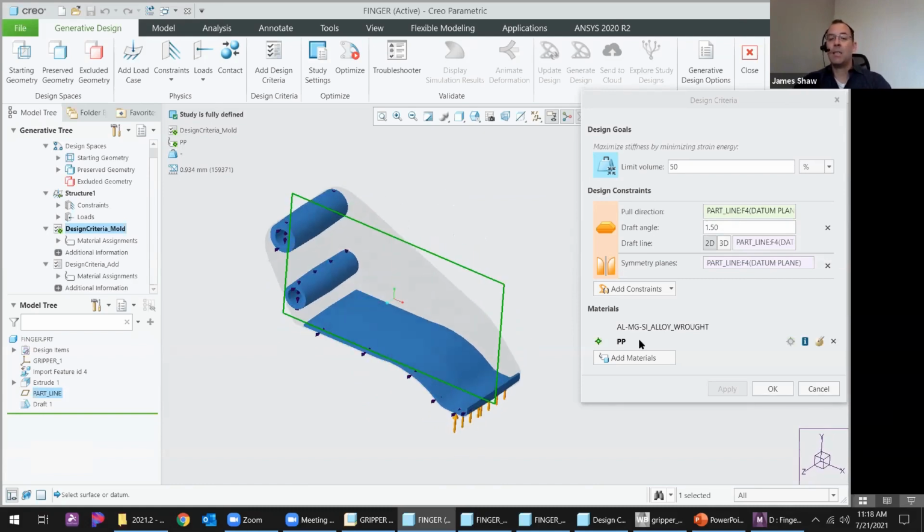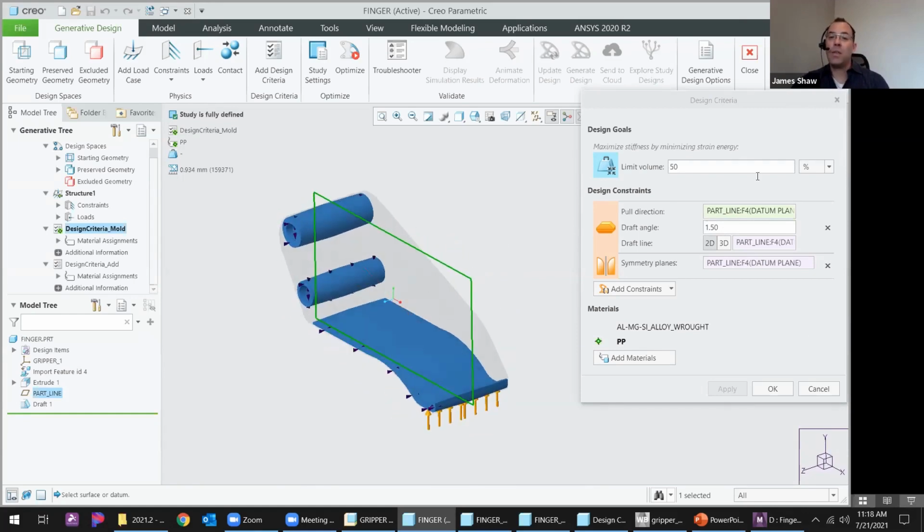In this case, I'm going to target a very economical polymer. So I'm going to go after polypropylene, PP. I'm going to hopefully reduce the mass by 50%, have it meet any of the molding requirements that I want, make it cheaper, and then make it out of PP and have it still be strong enough.